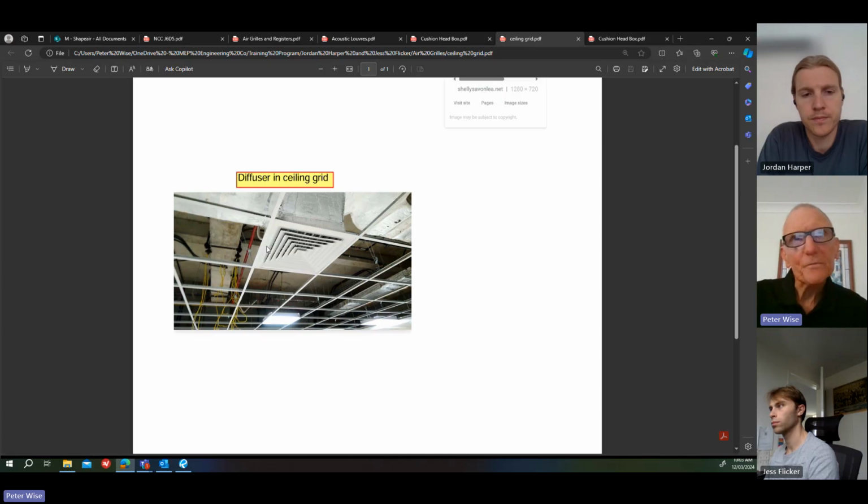And it's the same with where you can. Sometimes you can't do it with return air. If the return air volume is too high, you can't connect it with flexible ducts, because flexible ducts have a limit on how much air they can carry. Okay.